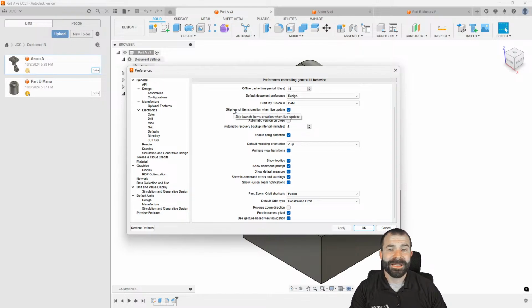This is very key. So the very first one is setting your actual button layout. Now, I don't know how much Autodesk is going to like this, but I personally prefer the SolidWorks button layout. And what that means is my middle mouse button allows me to orbit around my part and twist my part. Now, for some of you, you're going to pan and move with that middle mouse button, and you can use things like hotkeys like Shift and Control to cause other effects. Me personally, I like the SolidWorks hotkey.